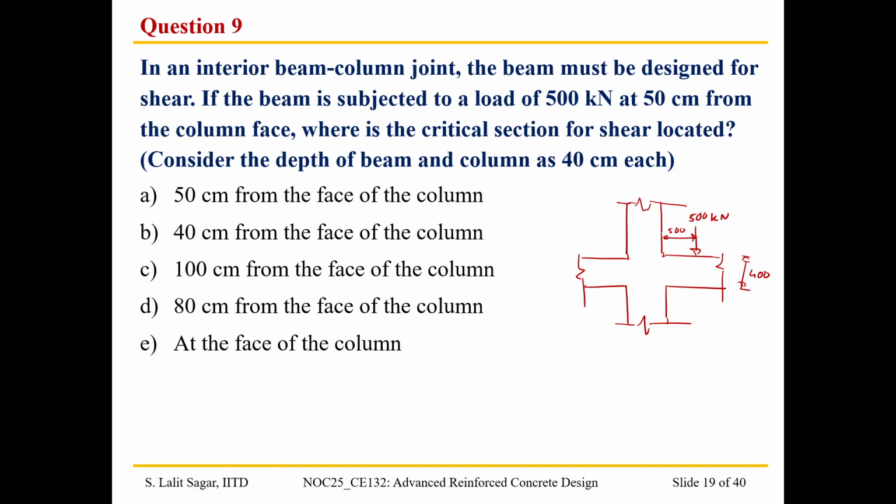So the question is whether you're going to consider the critical shear at the face of the column or at a distance of d from the column face. Let me call the face of the column xx, and we have another section at a distance of d from the column face, let us call it yy, at a distance of 400 millimeter, or any other cross section.